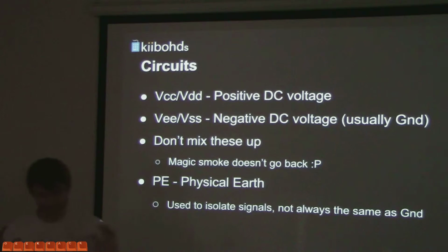When you first power on your keyboard, so you finally figure out where the power and the ground are, don't swap them. If you turn on your power supply and you plug it into your computer, there's a chance you're going to fry everything. You could fry your computer, because basically you have an open circuit that could just drain power. Computer shuts down, or something bad could happen. Might not, but it could happen. Probably a ground trace on your motherboard. That's true. This is how you get fire.